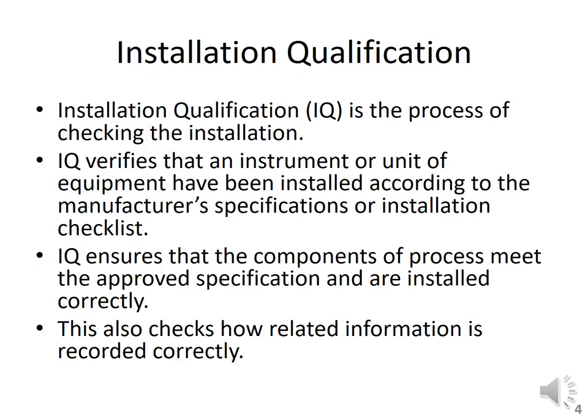So IQ verifies that all about an instrument or unit of equipment have been installed according to the manufacturer's specification or installation checklist, right? So whatsoever the specifications given by the manufacturer or the checklist provided by the manufacturer for the installation, your instrument or unit that you install is according to that specification or that checklist.